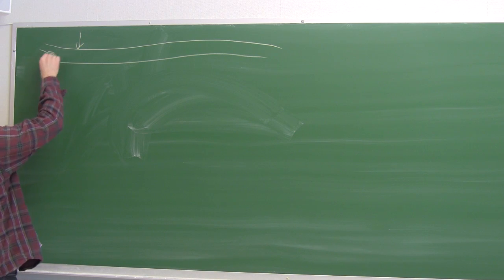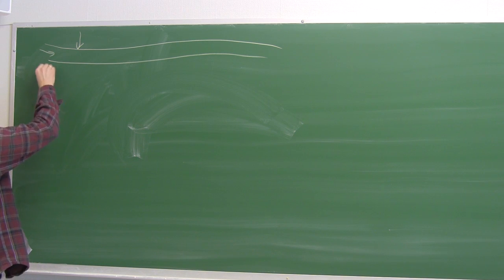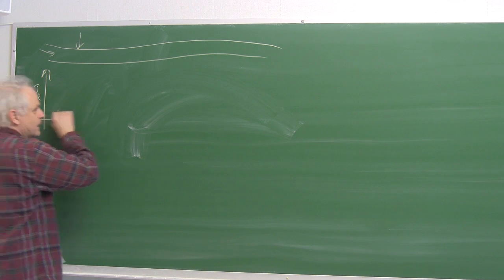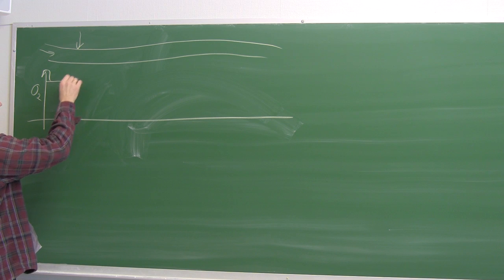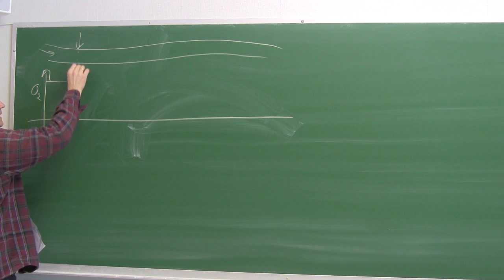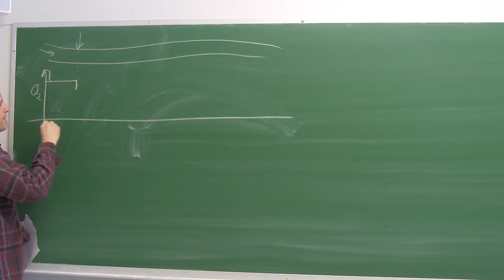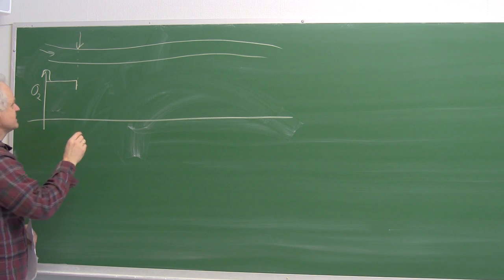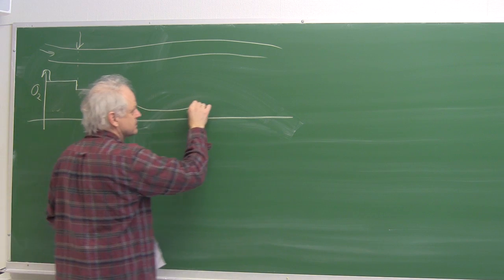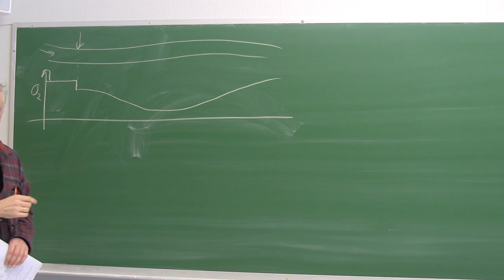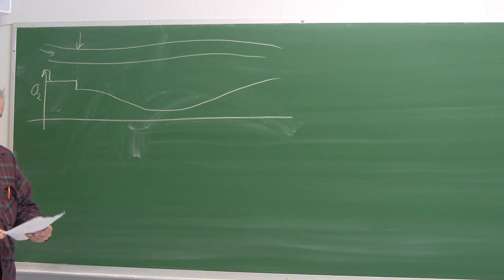So the river is flowing. We assume it's a plug flow type flow, and we expect there to be an oxygen profile that starts with a saturated level here, and then once the discharge comes in and mixes with the river, there is a drop. We will calculate that, which is easy, but the challenging part is to predict the profile of the oxygen downstream of this discharge based on standard mass balance analysis.